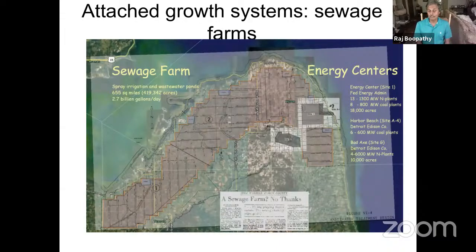So the sewage goes through, of course, the basic activated sludge process, remove much of the COD, BOD, and then instead of going through the rest of the steps, you go through the sewage farm, you release into a contained area and allow the plants to grow on it. Okay, so here is one in Detroit, Michigan, and people are doing this with a mild operation of sewage, and then most of it is released into the contained farm.